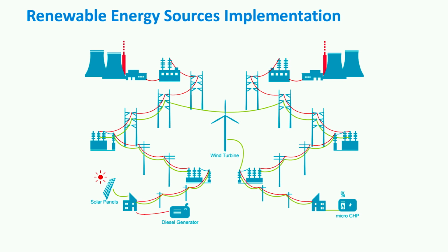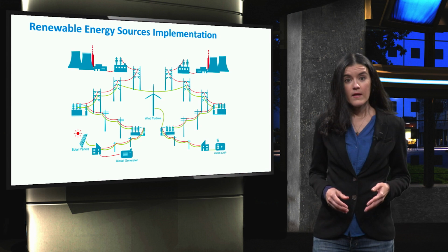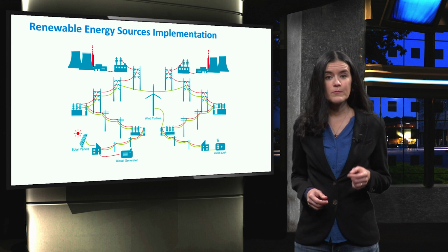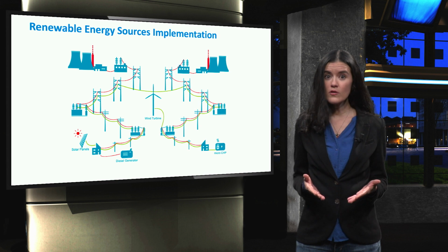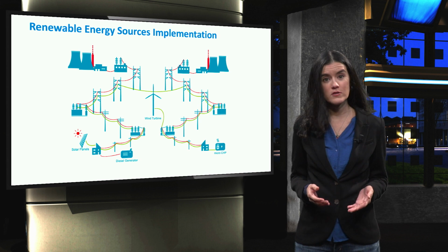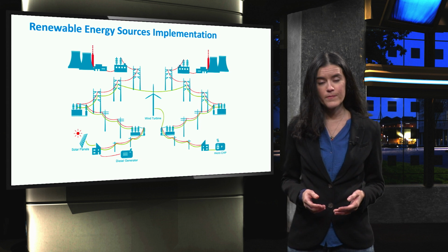Unlike traditional power systems, where there is a unidirectional flow of power from generation to distribution, power flows may become bidirectional in future power systems. The upstream power flow can cause protection and stability problems in the existing network because the installed equipment was not designed for such bidirectional flows.